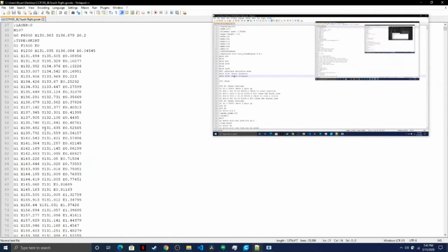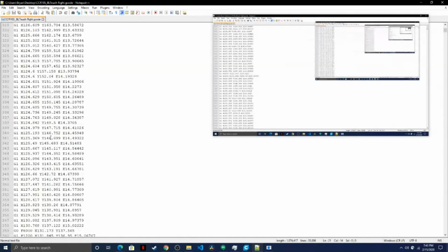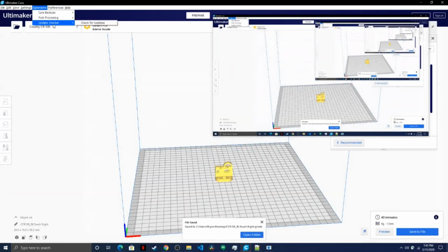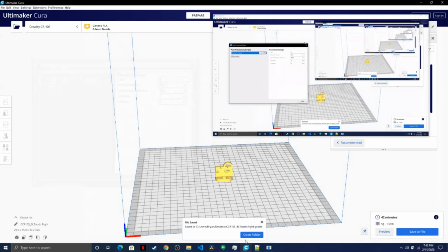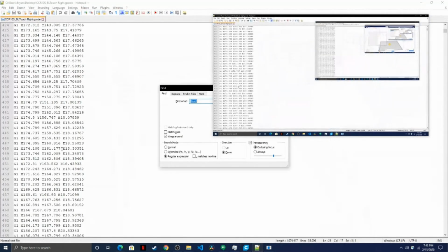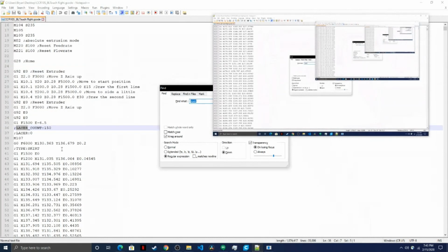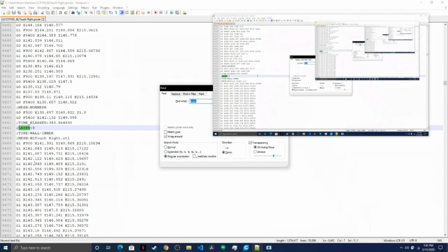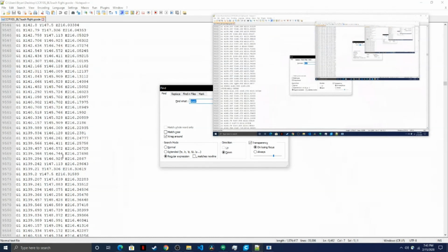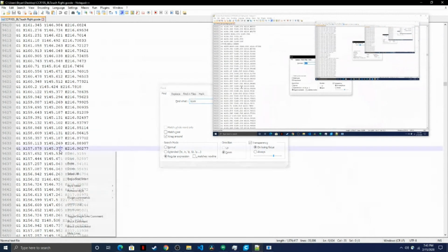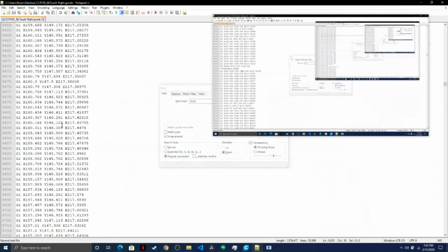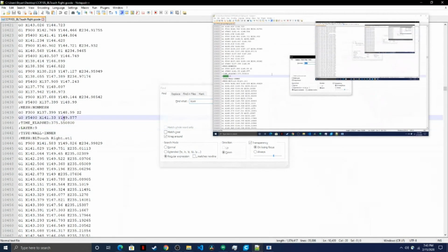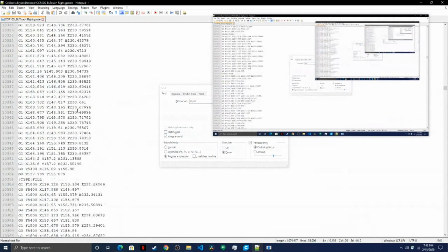Okay, so where's our filament runout change here? What height did we say that was at? That was at layer number 8. Let's find layer 50, 0, 1, 2, 3, 4, 5, 6, 7. Layer 8, wall inner, wall outer, wall inner, wall outer, wall inner. Let's go find layer 9. How about that? Let's see if there's a filament change.